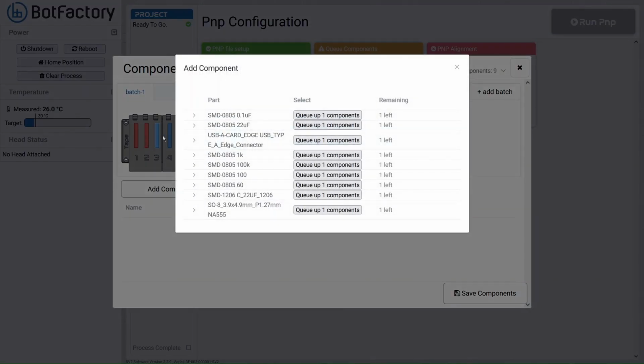I've got a couple of different resistors here. Since they have different values, they won't be on the same tape and will need to be placed in either two slots if they are on a tape. I have a lot of single components in this design, so I will probably put all of them in the single component tray. To be clear, you can place a tape with just one component at the top of the tape, or use just one component from the tape even if there are several on the tape. The printer will take whatever it needs.